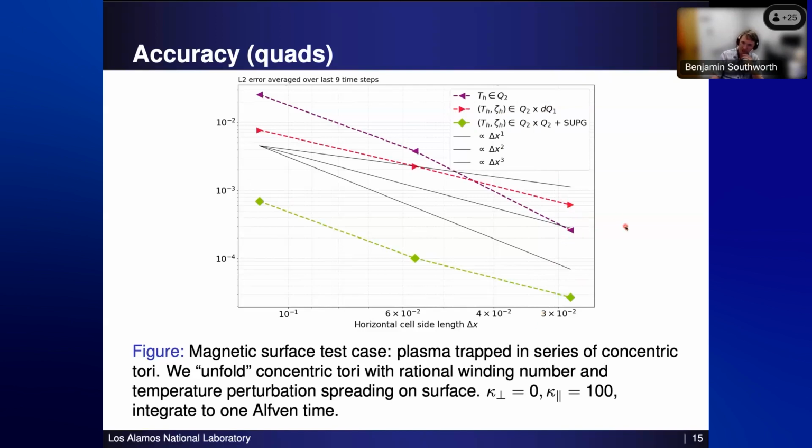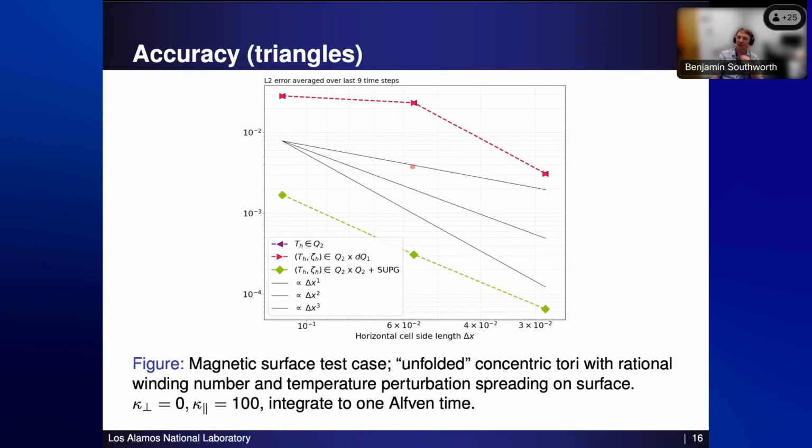What's interesting is it looks a lot better with triangles. I'm not sure why these existing schemes struggle on triangles, but they do. They prefer the quads a lot, and our new scheme is pretty much indifferent. From a computation perspective, I appreciate triangles because everything's affine and it makes it easier to assemble things, or cheaper anyway. So here we're getting, at this point, not quite 2 orders of magnitude, but pretty close, better error using our new discretization than existing methods in the literature.